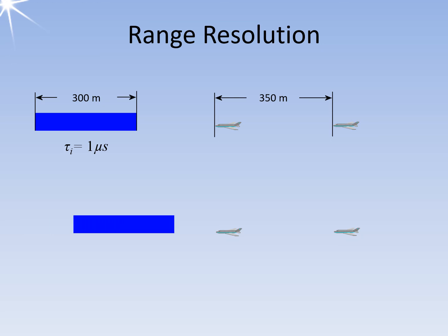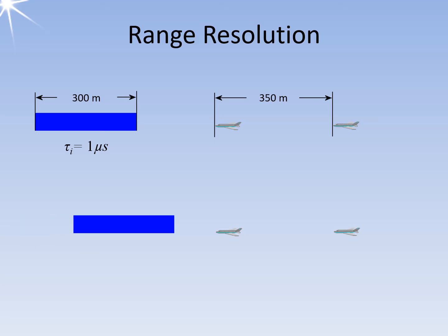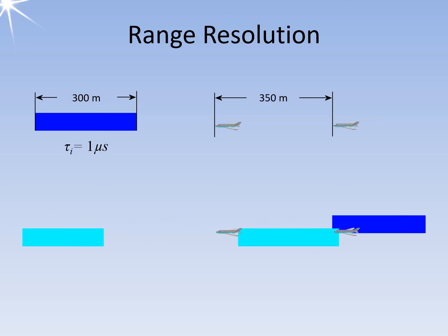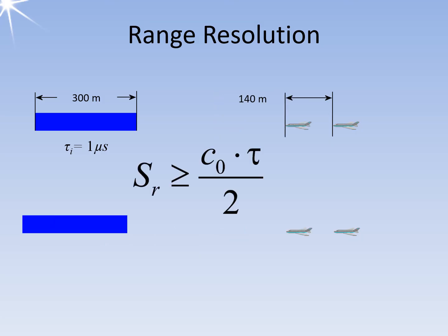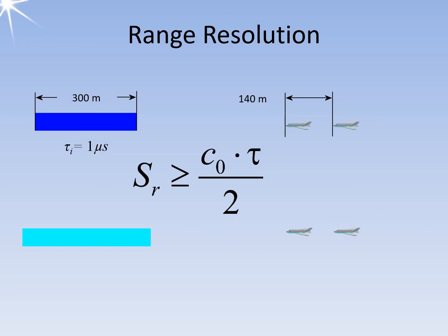Note that here, the length of the impulse in the space is not divided into outward and return paths. Therefore, the 1 microsecond still corresponds to 300 meters. Here, the animation shows the case with a smaller distance than 150 meters. The radial range resolution is the limiting case where two echo signals are separated and processed as two target echoes.